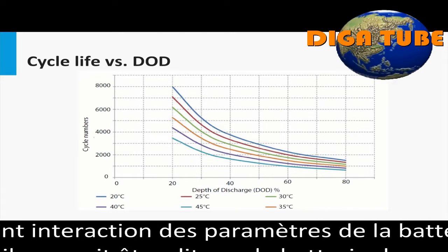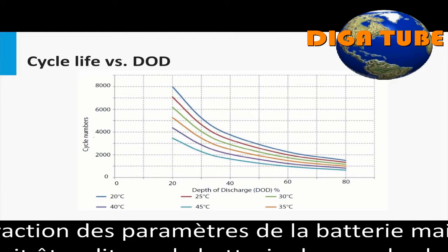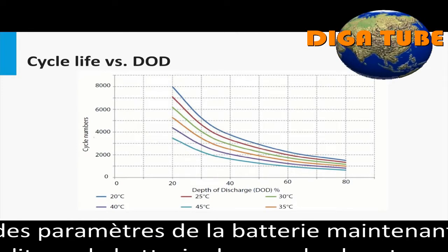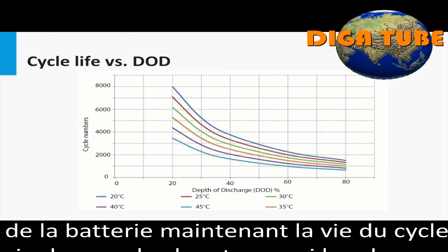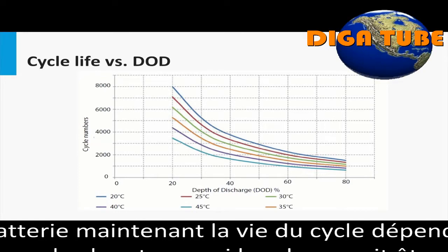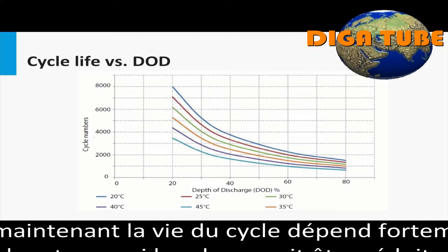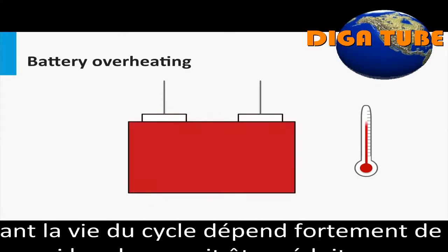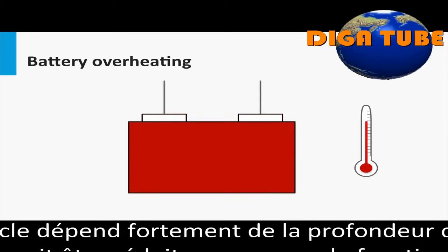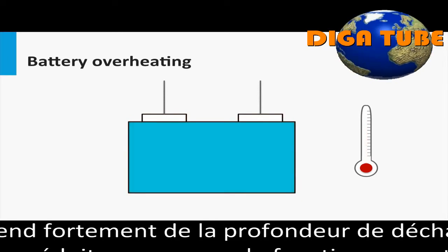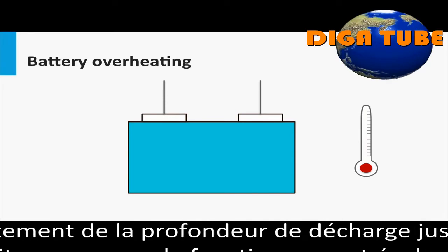The smaller the DOD, the higher the cycle life. However, such a higher cycle life would also mean that those additional cycles you gain can only help you for a smaller depth of discharge. Thus, it could be said that the battery will last longer if the average DOD could be reduced over its normal operation.